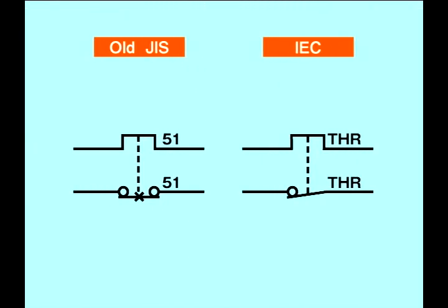In these circuit diagrams, 51 and THR indicate thermal relays. In many cases, the thermal relay is incorporated in the MCCB and electromagnetic contactor. A variety of sensor switches are used in the sequence circuit. With sensor switches, the relay operates when the temperature, pressure, or water level reaches a preset value.